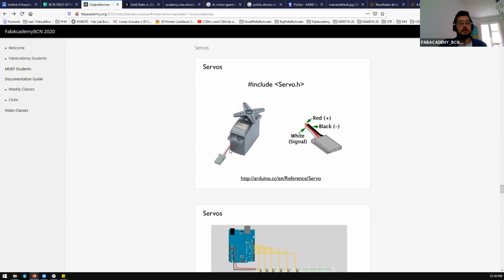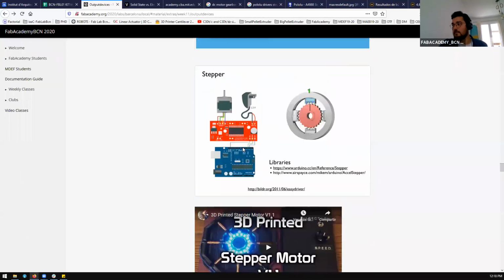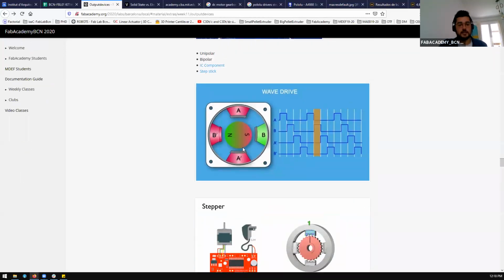Servos are much better. Why? Because most of the component is a DC motor that is on all the time. But this stepper motor is the opposite. You have kind of 2 DC motors, but you only use 1 each time. That's why stepper motors weigh a lot but don't produce that amount of torque, even if they have torque. A DC motor of the same size as a stepper usually produces double the delivered power.